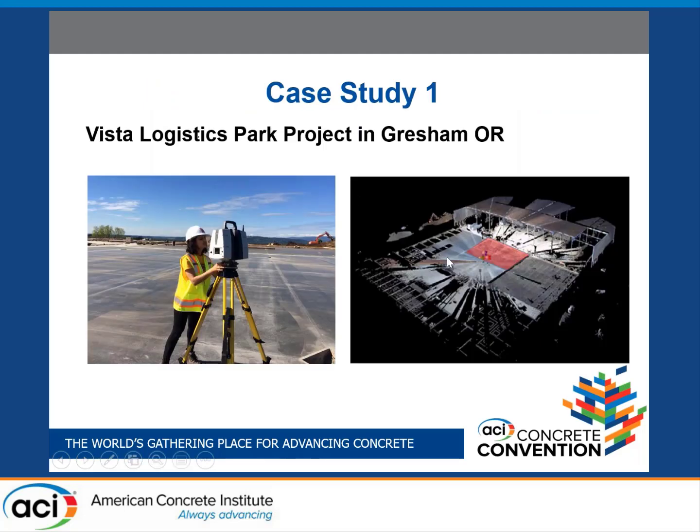This is the first case study I wanted to talk about. We collected data from a concrete warehouse project. This is a concrete slab. We used a terrestrial laser scanner, a Leica P40, one of their recent products. We did the scanning within 10 hours after the concrete was poured. The whole data collection, with all the setting up and everything, took about 45 minutes, which is faster than collecting data using the traditional methods for waviness measurements.